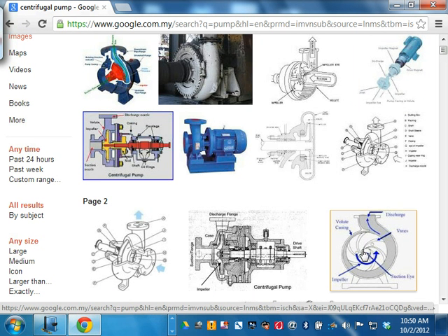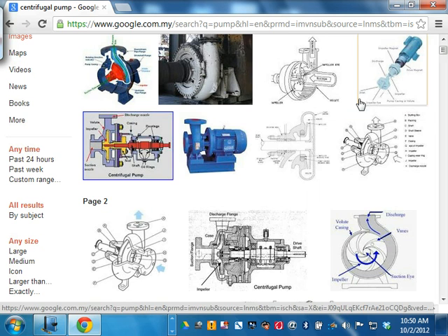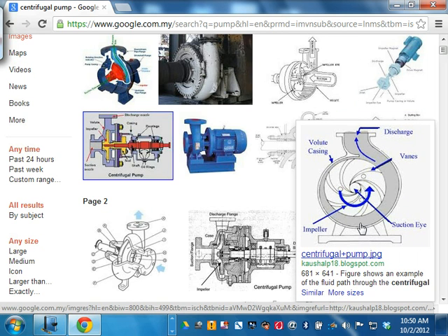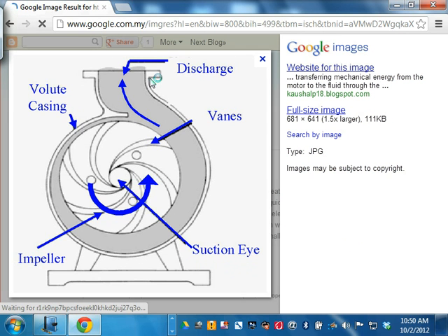So why is because here, that's the pump. The flow comes in here, spins, and goes out. At high flow rates and low flow rates, let's start with no flow rate. You put a valve, you turn it off, and you let the pump spin. It gets hot now, so don't do it too long. It might damage the seals and so on.